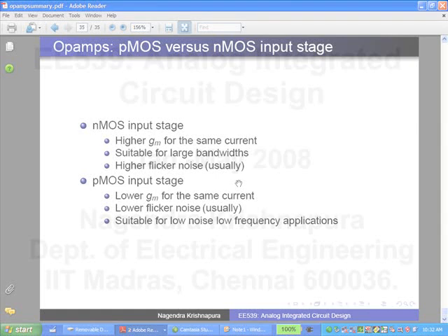That's the trade-off. So basically, if the pole associated with the load capacitance is the dominant pole, then there is no problem. You design it for the lowest value of the load capacitance. Then as the load capacitance increases, the dominant pole only moves inwards. In that case, you will only lose on bandwidth. You will not have any problems with stability. Whereas in a two-stage op-amp, the load capacitance is associated with the second pole. If that pole moves inward, then you will have a stability issue. So usually you can only design it for a certain range that is known.